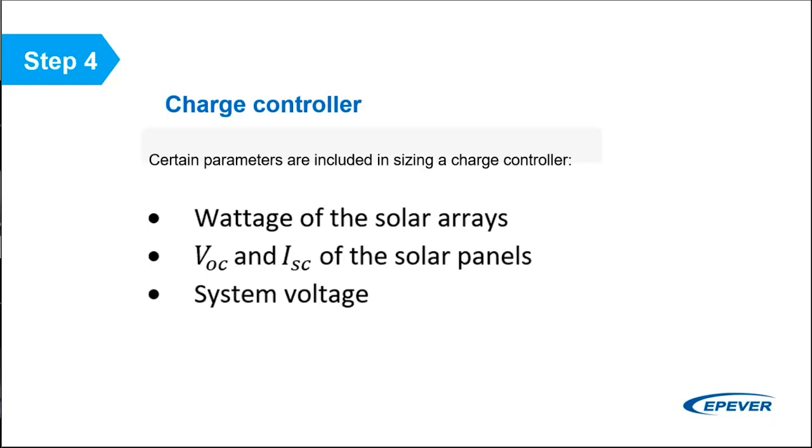But MPPT is a charging control technology that ensures delivering the maximum available power from the solar array to the charge controller. Unlike PWM controllers, non-matching voltages from the panels and the batteries are not a concern, because the MPPT charge controller will convert the extra power from your PV panels to current, so that you have less loss in your system.